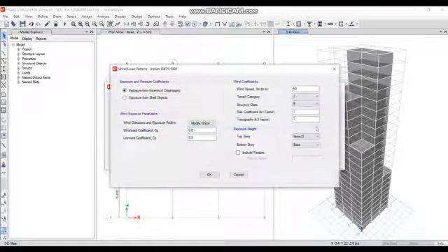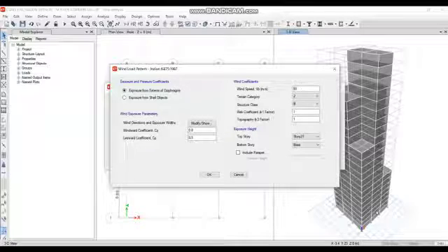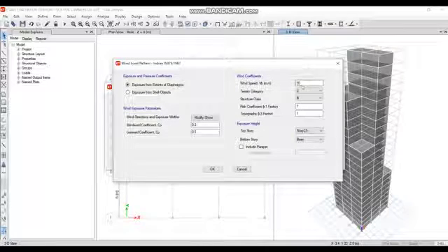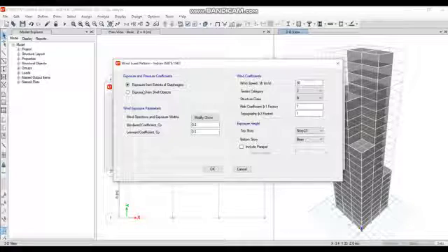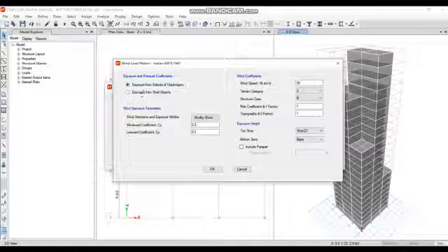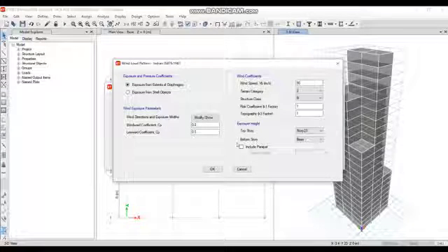Go to the modify lateral load. You have to refer to IS 1875 Part 3 and open the map. I am opening the hard copy, so I am not showing it here. I don't have the soft copy of that particular IS code. So open the map and consider the building to be designed in Bangalore, as given in the problem statement.